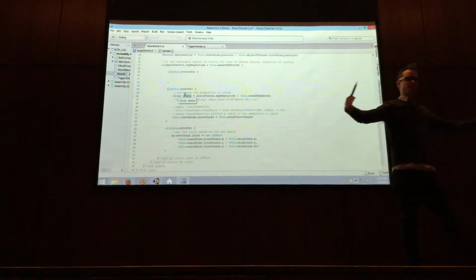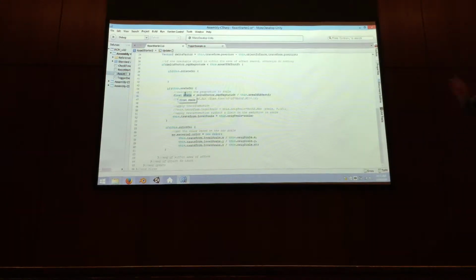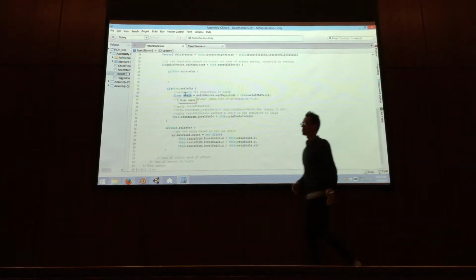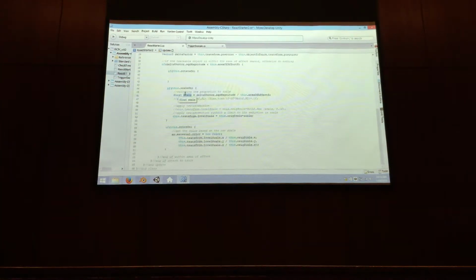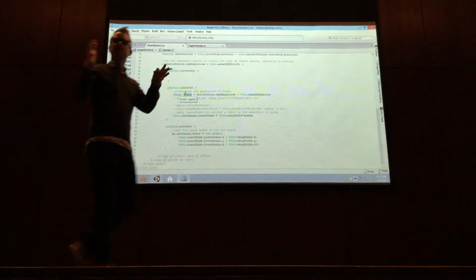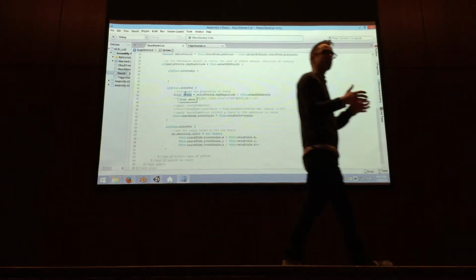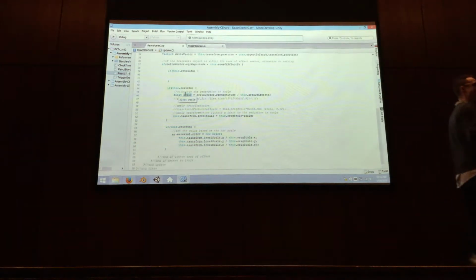I know that the area of effect is 5. And I know that when I hit that point on the edge, my vector is going to be 5, magnitude of 5, right? So when I'm on that edge, this object will be scaled with 100%. And if I'm halfway, I'm at 2.5 magnitude, 2.5 over 5 is half. So now it's going to set my scale factor to half. But it's a question of half of what? Half of that original size, which is why I need to remember it.